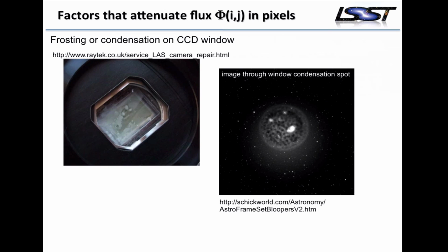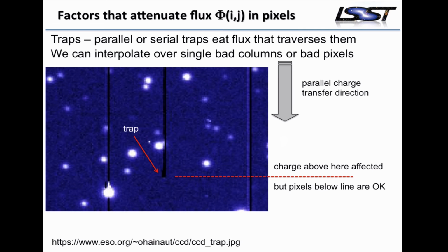Another thing that can be a bad thing, shown on the left, is a really delightful picture of a contaminated Dewar window and detector, right? So if there's contamination in the optical train, that's really nasty and bad. And on the right-hand side, although it doesn't come through particularly well on the screen, there's a funny halo of crud here that's actually light from this bright source propagating through contamination and crud. So it has a pretty distinctive footprint.